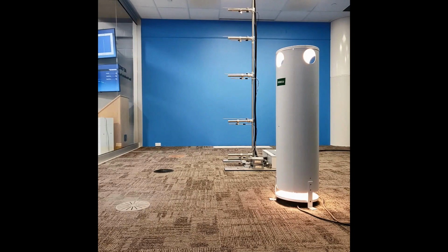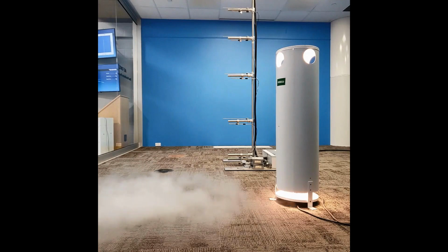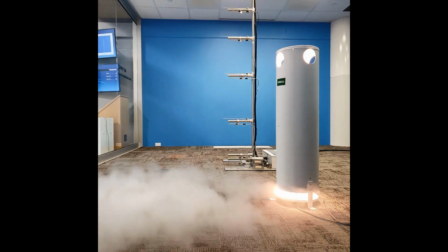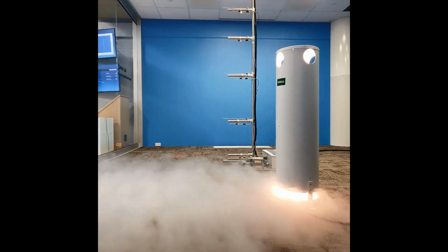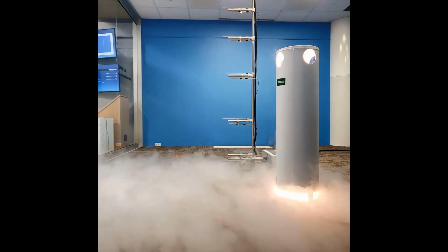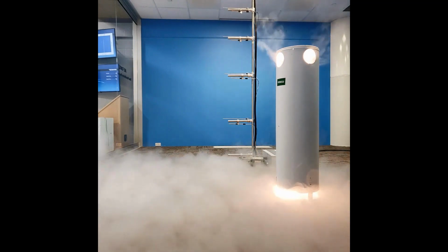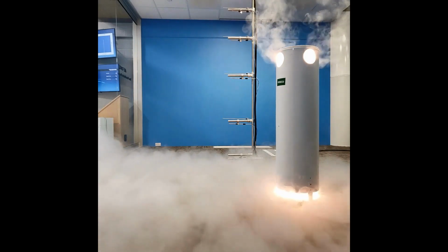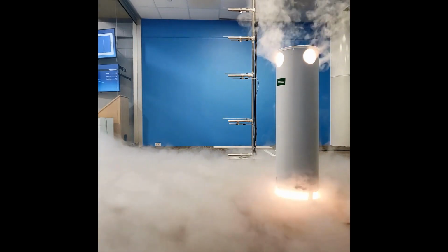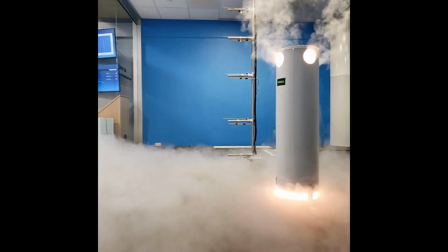These are the ones that we install in auditoriums and conference halls that are within a foot of the occupant's ankle region. And you really minimize your draft concerns with the low turbulence that is witnessed by these diffusers. But don't be afraid to mix and match a displacement round floor with a twist diffuser. And you can put these in the areas where they're most likely required.